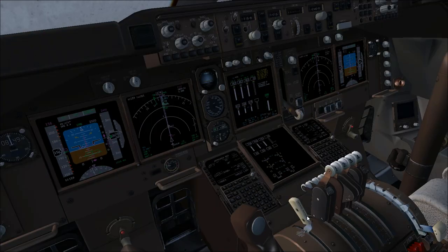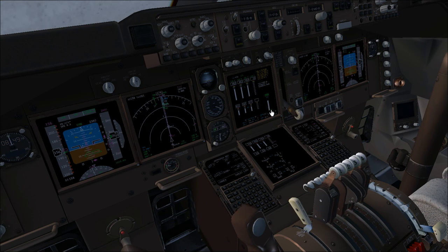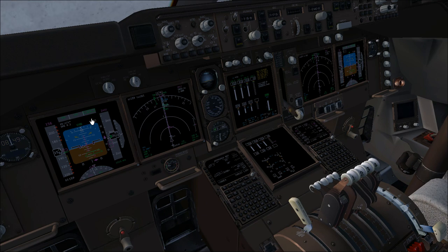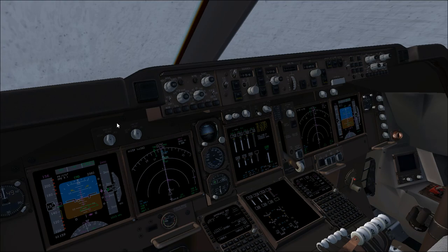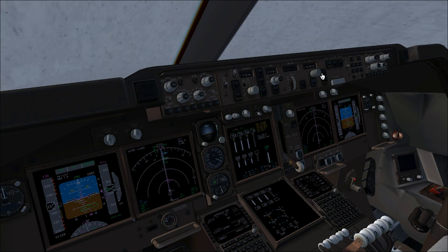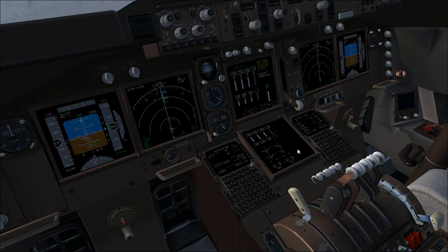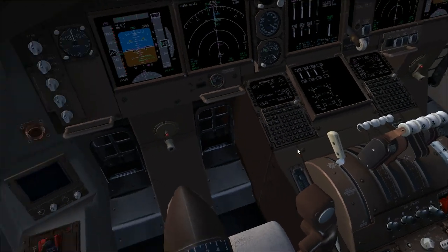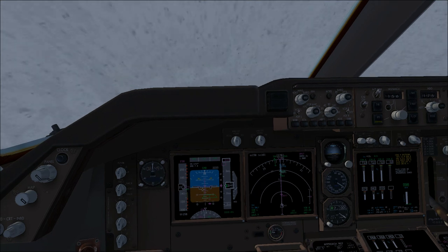Before landing checklist: speed brake armed, gear is down, flaps are 30, and glide slope is captured. Now that the glide slope is captured, you have to select the go around altitude. In Porto it is 3000 feet. 3000 feet set on the altitude window. Auto brakes are 2. Sign is okay. Cabin is prepared and ready for landing.